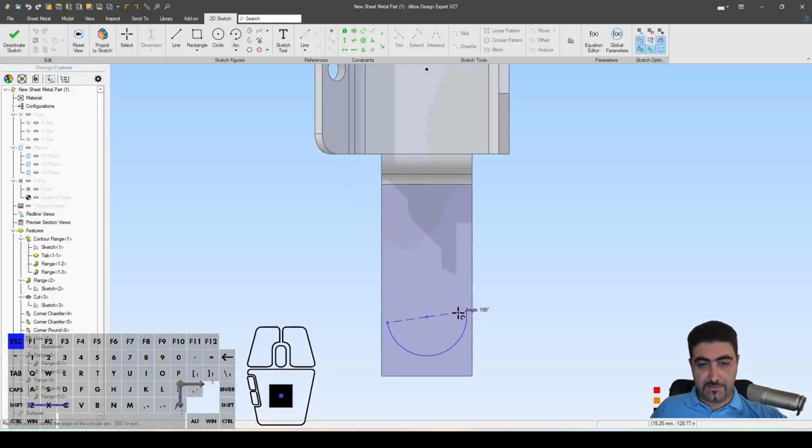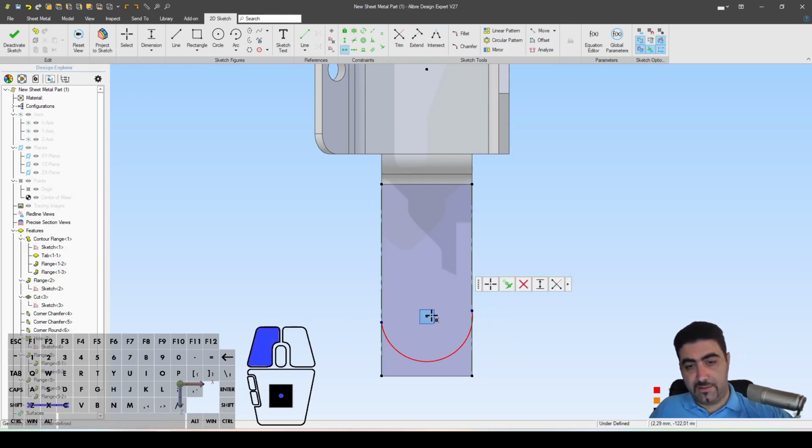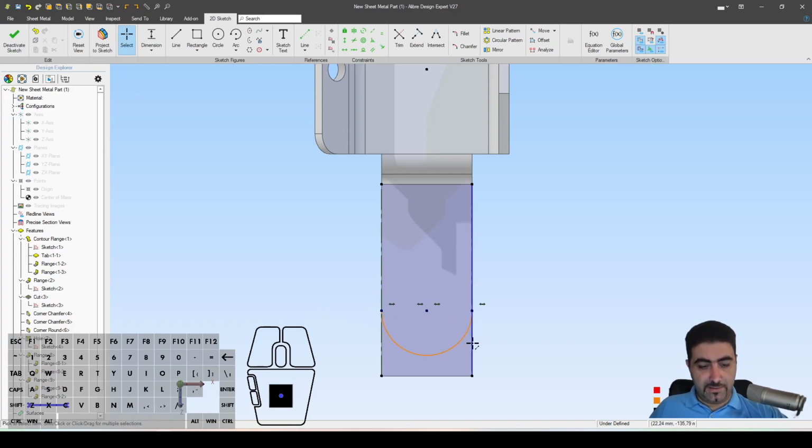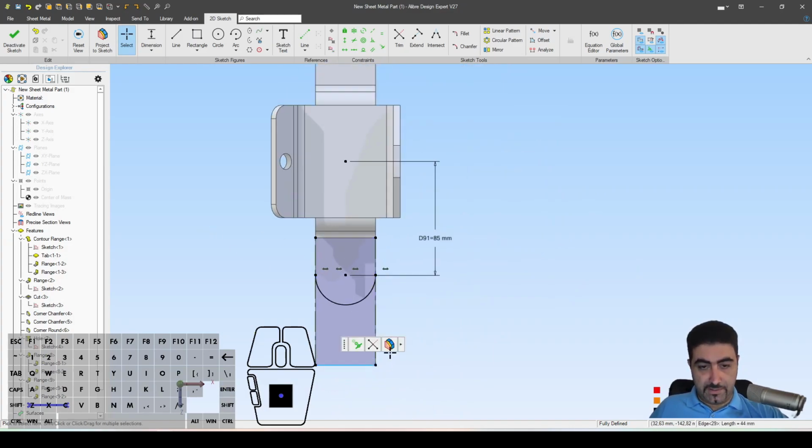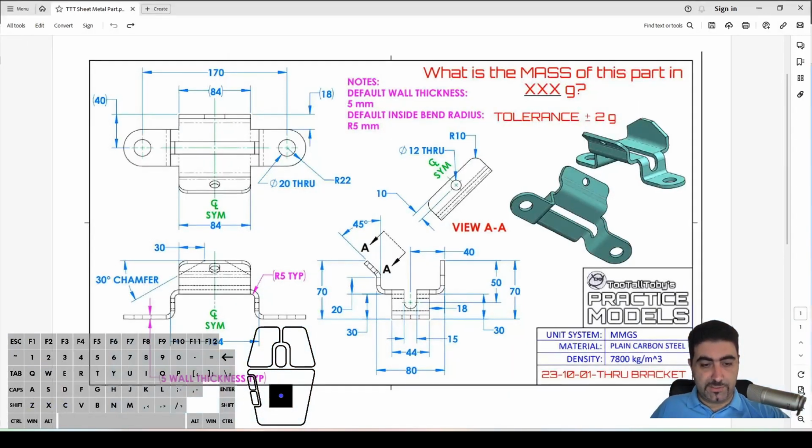Okay, let's start a circle with a center and 2 points. Then we need to make all of that horizontal. Okay, and then we need to make sure that this is 170 divided by 2, which is 85 millimeters. Okay, now I need this to be a geometry line, and I need a couple of lines to connect that, plus a circle here, and that was 20. That's a 20 millimeter cut.